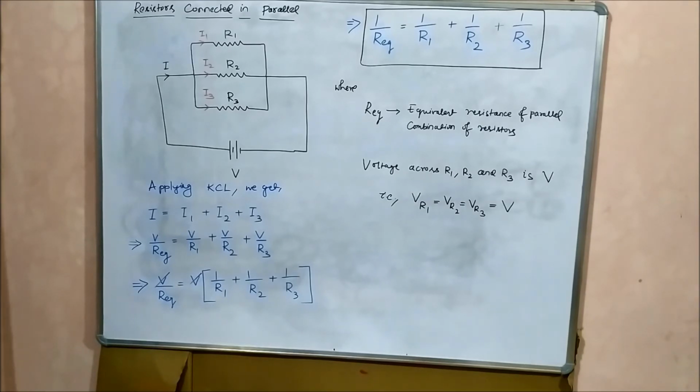When you see an end-to-end connection pattern in resistors, meaning the right end of a resistor is connected to the left end of the next resistor, and again the right end of that resistor is connected to the left end of another resistor, then we can say that the resistors are connected in series. And in series connection, the current flowing through the series connected resistors is the same.